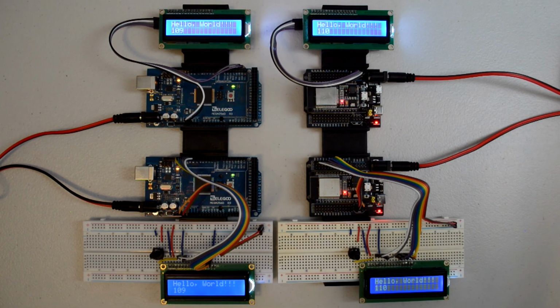Since LCD modules that support I2C are inexpensive, I choose them over modules without I2C for prototyping since they result in significantly simpler wiring, which typically means that there's less of a chance of things going wrong, like having a wire get disconnected. Links to the code examples and diagrams used in this video are provided in the description.